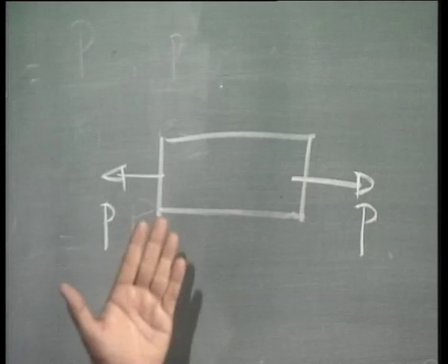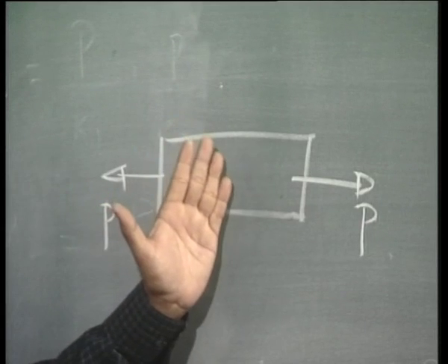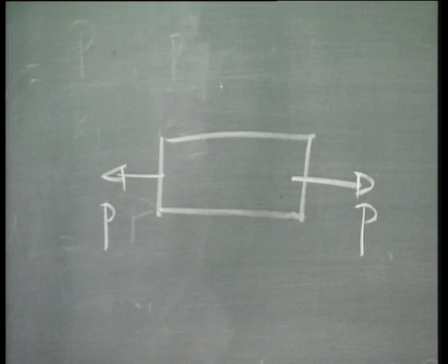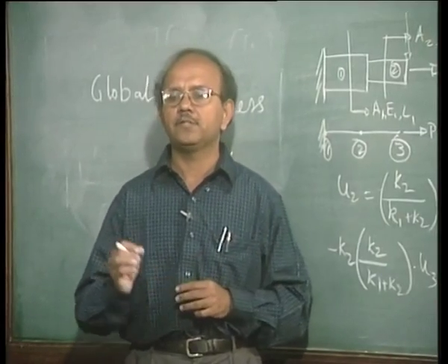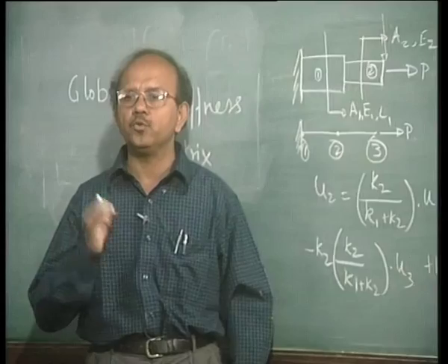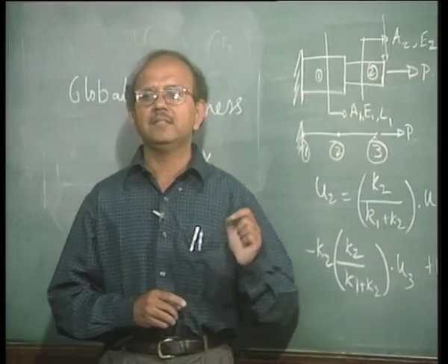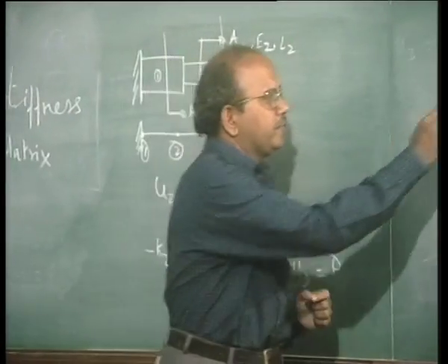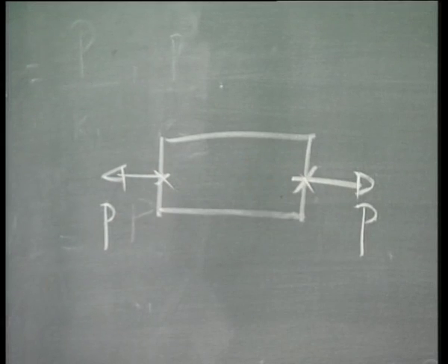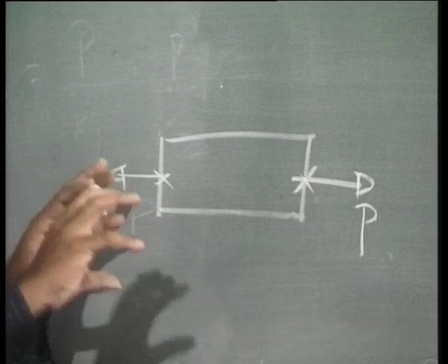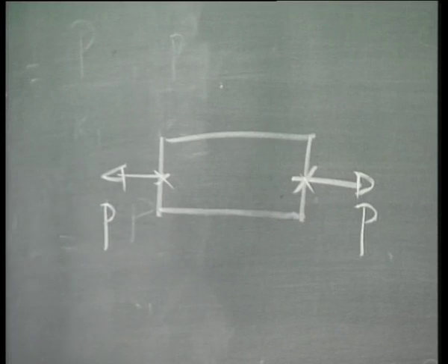Because you have got these particular equations for the stiffnesses from just the internal equilibrium, right? So in other words, the solution for this problem, as far as, say, for example, displacement is concerned, will not be unique. Physically, what does it mean? It means that I have to get the correct positions of these, for example, ends as I apply the load in this bar. Now, that is not unique. It is something like adding a constant to an integration, right?